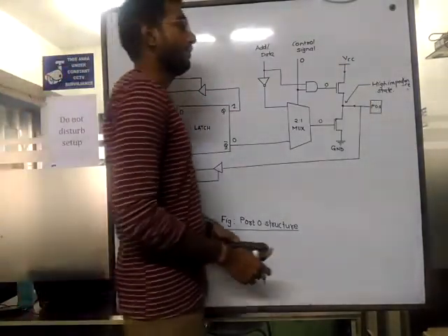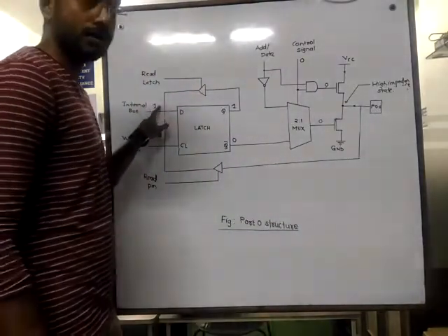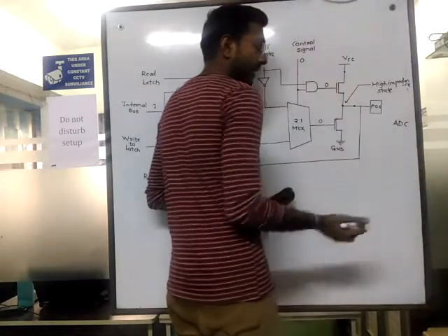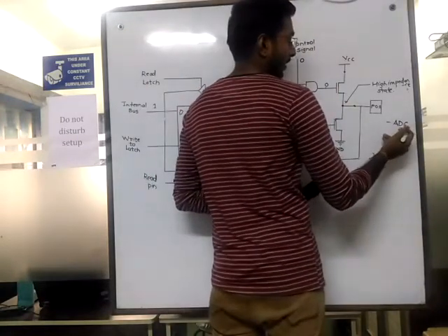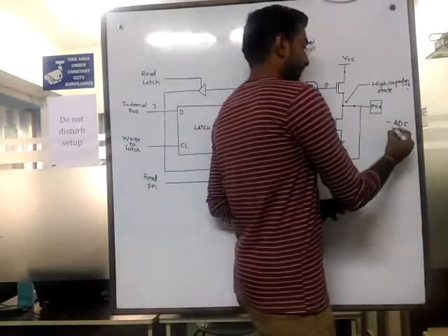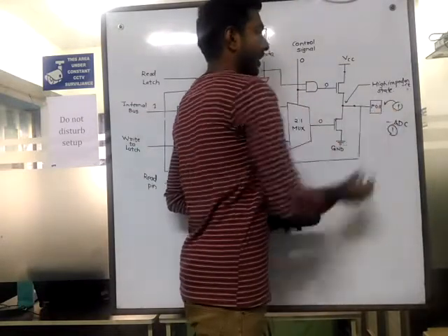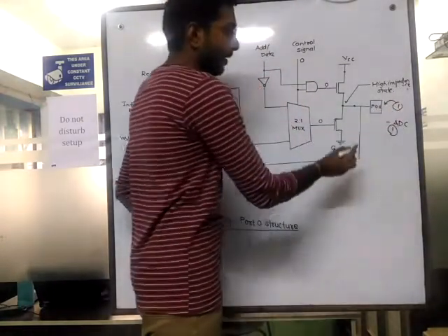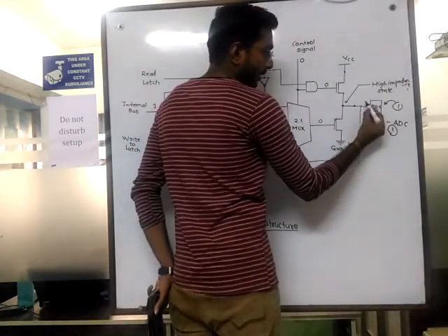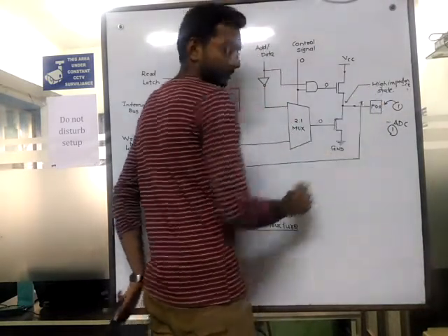So if we want to get input, because we are configuring this port as an input, let's say we want to take input from an ADC. If we are connecting this device, an analog to digital converter, and we want to take bit 1 from the ADC at this pin, whenever 1 is written here, this one will override this high impedance state.